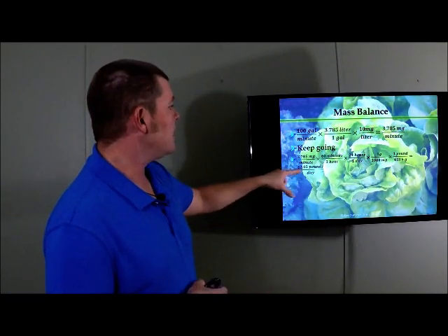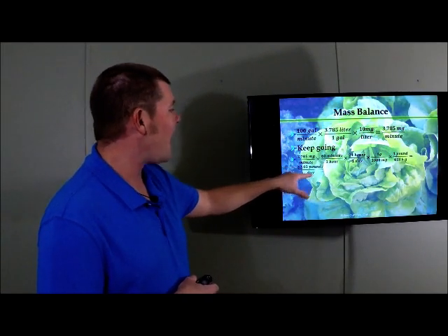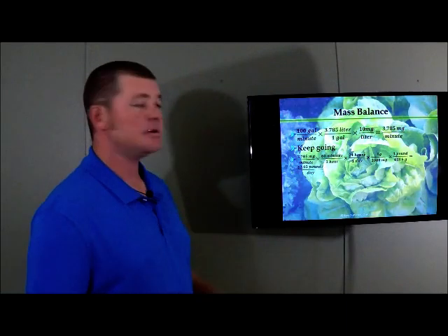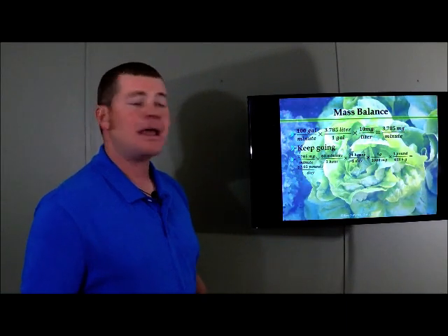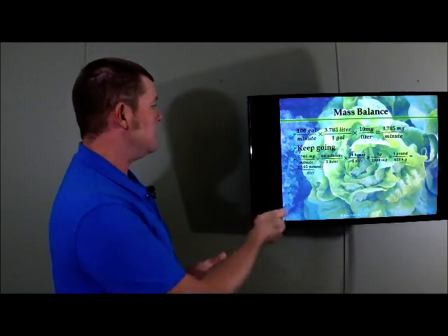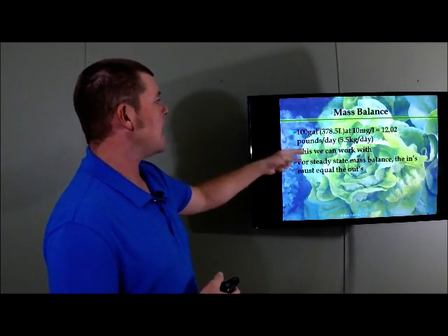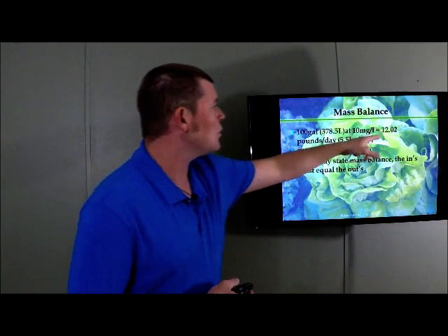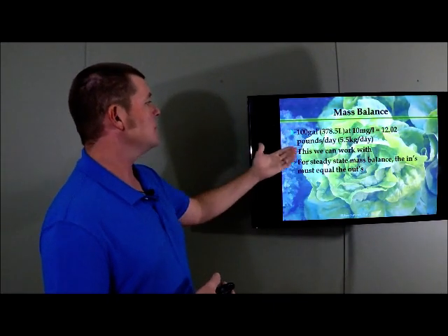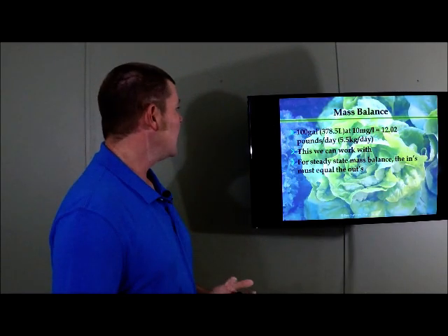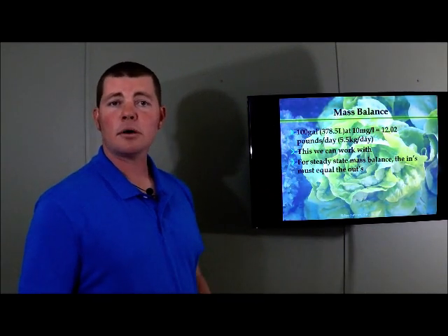And you're going to get 12.02 pounds per day. 12.02 pounds of oxygen per day is what you actually need. So we've got 100 gallons at 10 milligrams per liter equals 12.02 pounds of oxygen per day, which is 5.5 kilograms per day. This is something we can work with.